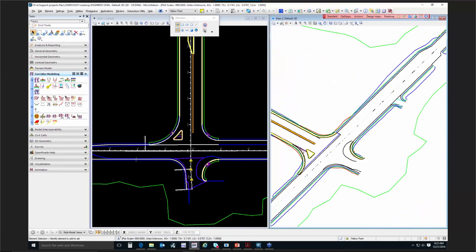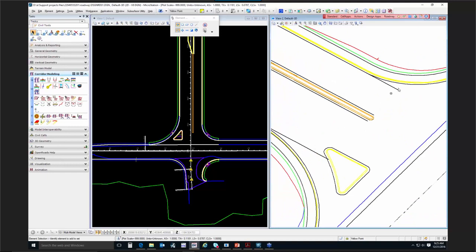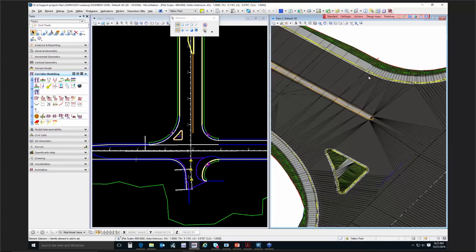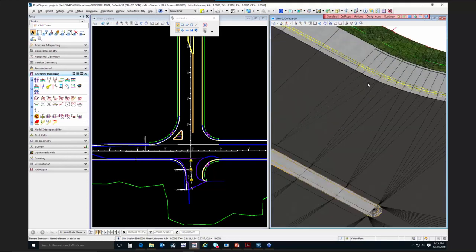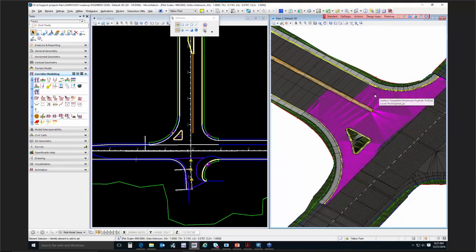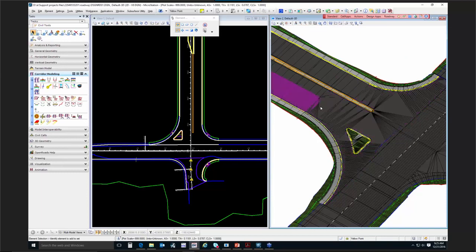So these are the kind of things that contractors are finding when we deliver our line work, is that, you know, this is really not acceptable to them, because when they go to create a terrain from these top lines, it tries to add in this extra break here, which we never really intended. And if you turn on the shapes again, you don't necessarily always see them the way we model certain things. Either that, or you've just got to get more cognizant of what we clip or what we create.